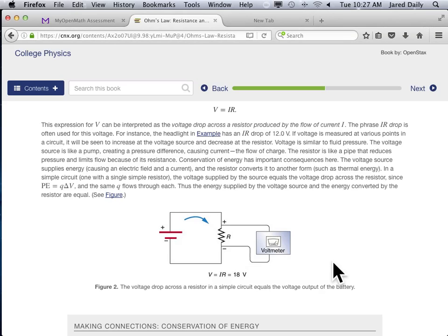Ammeters are not designed to check something on either side of an element. They're designed to replace a wire or replace an element in a circuit. So you actually put them into the circuit and let the current flow through the ammeter, and then it can measure the current. Current meters or ammeters have very low resistance. And so if you drive too much current through them, you will heat them up and they will burn out a fuse usually. Most ammeters are built with fuses these days so that you can't hurt the meter, you just hurt the fuse.